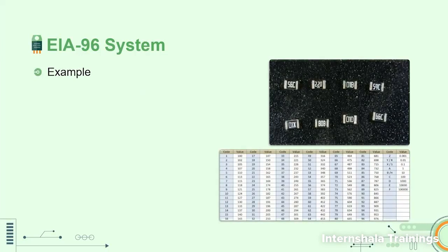So these are some SMD resistors that I had with me. So let's calculate the values for all these SMD resistors one by one. So let's start with this particular resistor now. And remember, all these resistors that you see have the package of 0603. So in case of the first resistor, on top of it, it is written 56C. Okay. So you have to look for the first two digits, and you have to check these two digits in this table. Now let's look for the 56. Okay. So you can see here 56 is written here. Okay. The value is 56. Sorry, the code is 56.